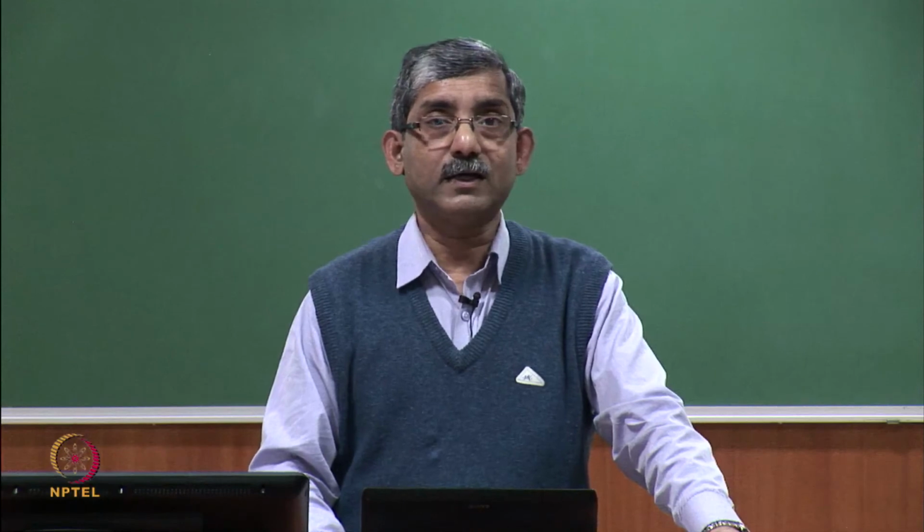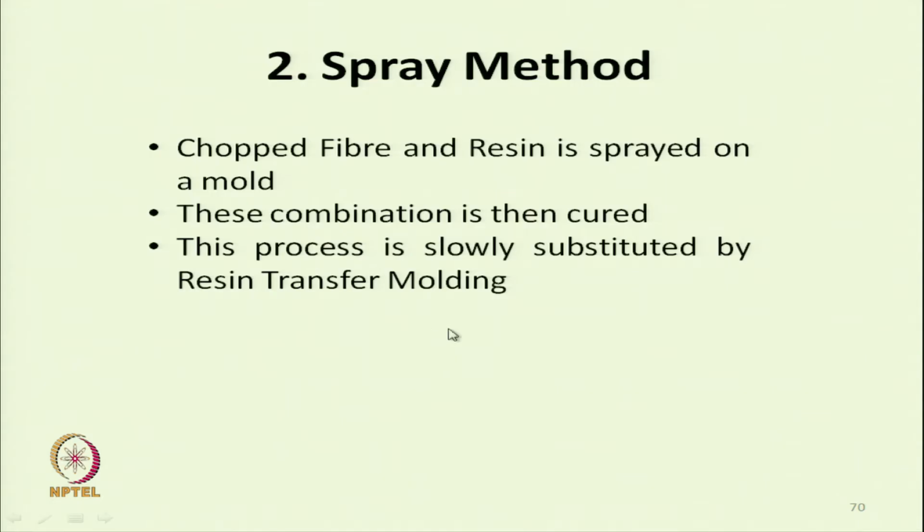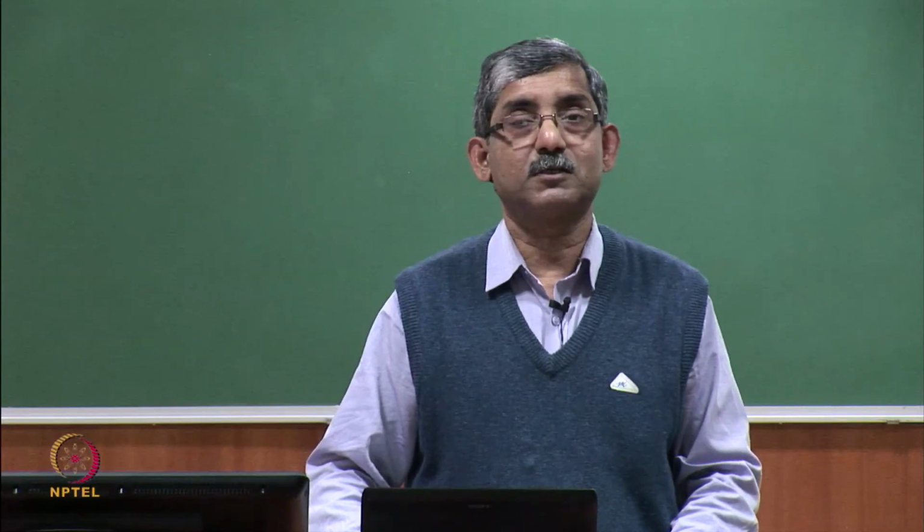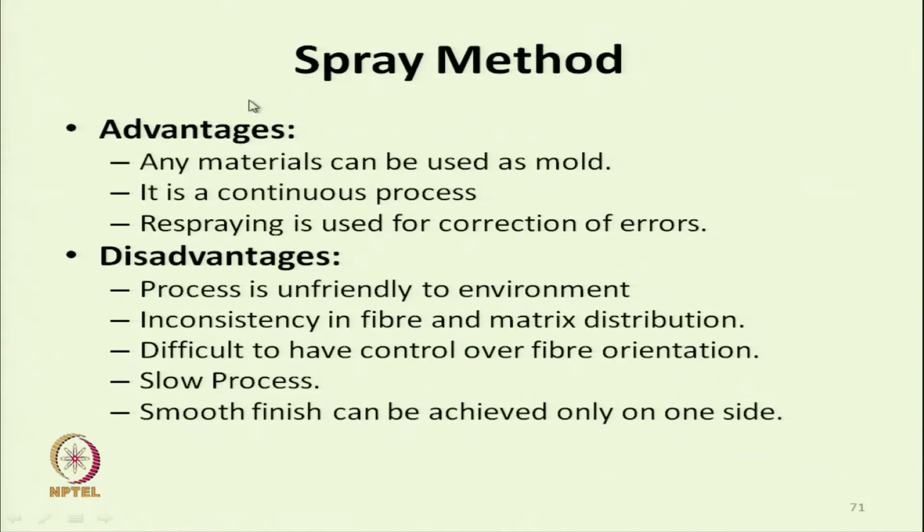In RTM, resin transfer molding, the chances of void content are less, but still, due to its simplicity and flexibility, we still use this spray method.